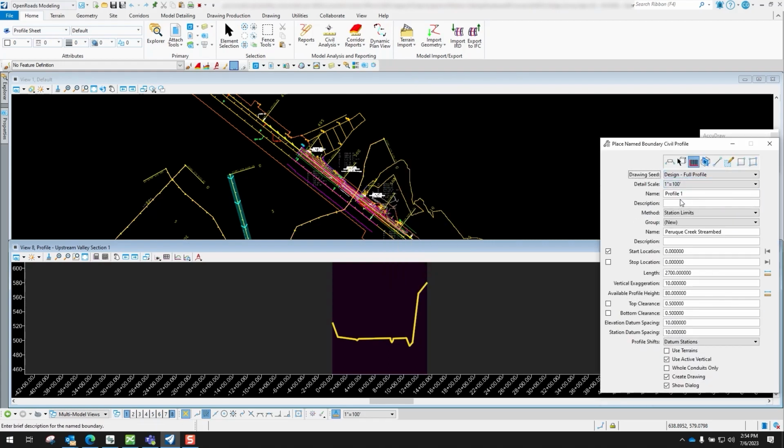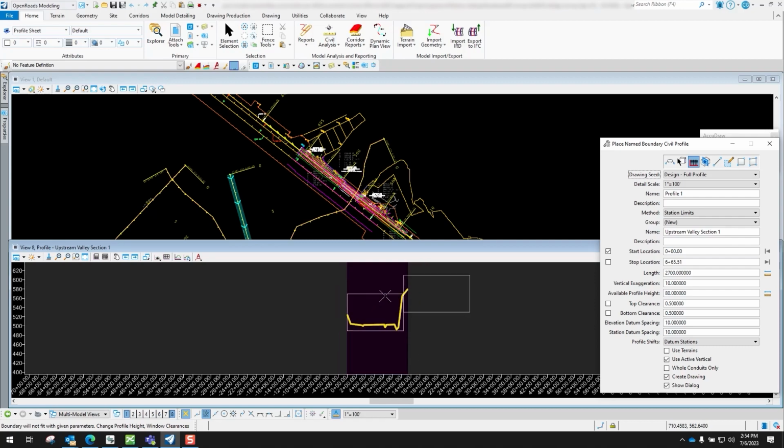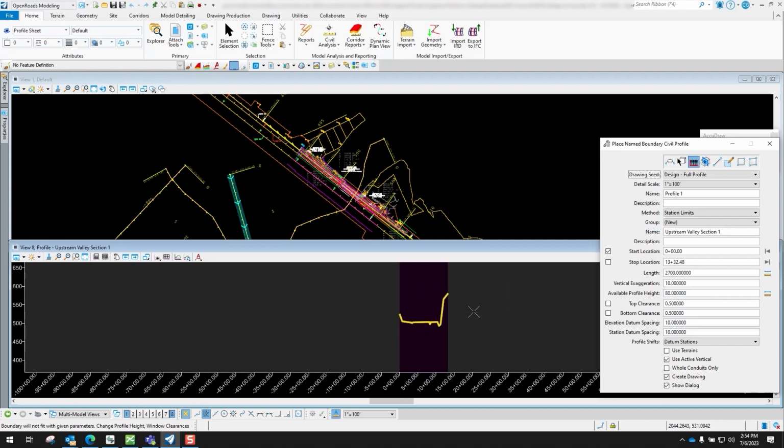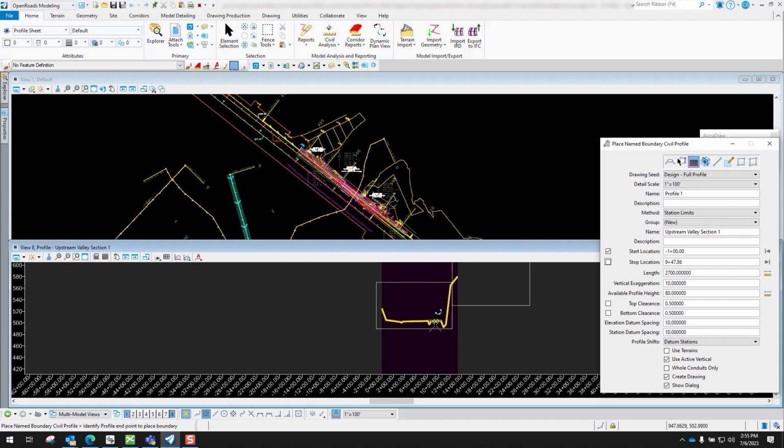we'll come in here, leave that set. First thing we'll do is identify our profile view, which is right here. Where's our start spot, which is right here, so I'll snap that spot right there. And now you'll see that our coverage right now is just like the way it's set right here for both of those. So what we can do is come in here, and let's say my start spot, maybe I want to go -100 off that spot also, so I'll go -100. Tab to lock that in. You see that I got a little bit more coverage here.